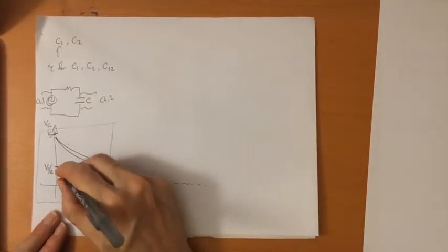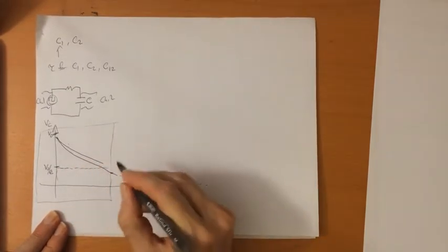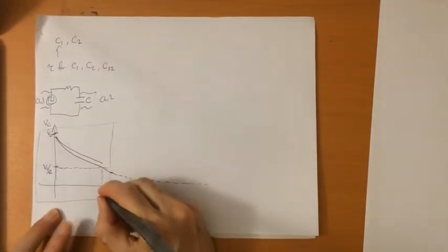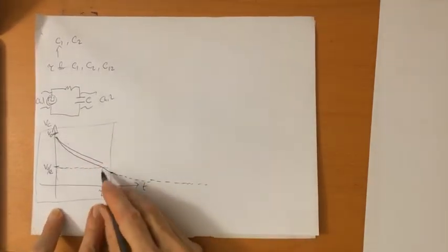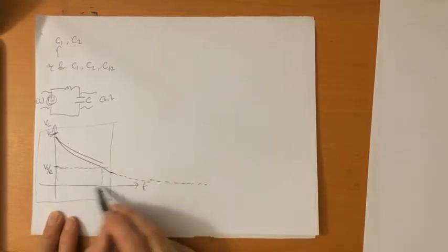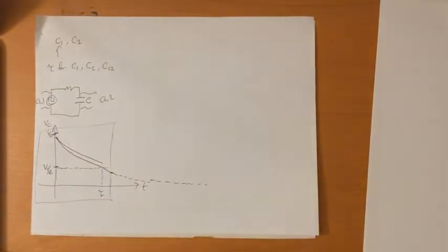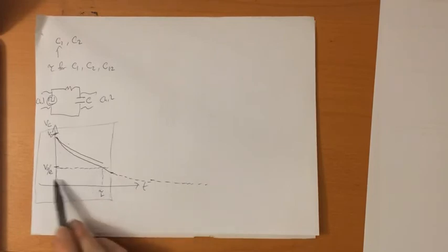You divide that by e, and then the idea is if I were to map this over, then this should be the time constant here. And so this gives us a way to actually measure the time constant. I'm then going to show you how to get this with cursors.